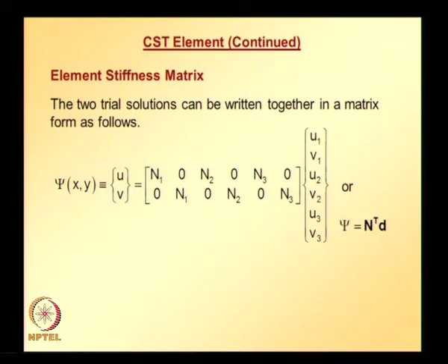And here this is how displacement in x direction and y direction can be interpolated using finite element shape functions and nodal values. But if you go back and see the strain energy equation U, it consists of strains. So, in order to use potential energy functional, the strain energy and work done by the applied forces must be expressed in terms of displacements or in terms of nodal unknowns. Strain energy in terms of nodal unknowns can be written